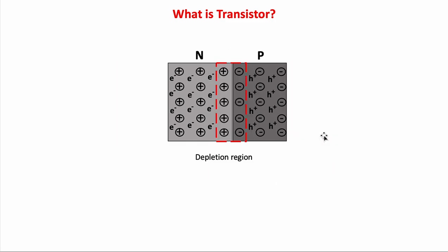So when a P-type and an N-type semiconductor are joined together, a carrier-free region called the depletion region forms around the junction. In this region, only ions remain, acceptor and donor ions. So it acts as an insulator barrier, and this also prevents the current flow under equilibrium conditions.